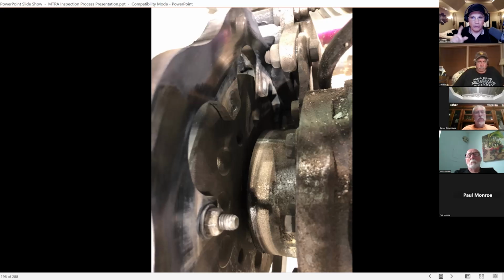You notice here, when you do your inspection, you want to look and make sure all the bolts are there. A lot of times it's not neglect. Sometimes these things get hot. That's one of the problems with the brake system, is that they generate so much heat that even using grade 8 bolts and everything, getting those things red hot like that, they lose their temper right quick. So they need to be watched quite often. They need to be checked weekly or nightly. If it's multiple performances over the weekend, you want to just quickly look. It takes 5 seconds to just look and make sure everything's there.